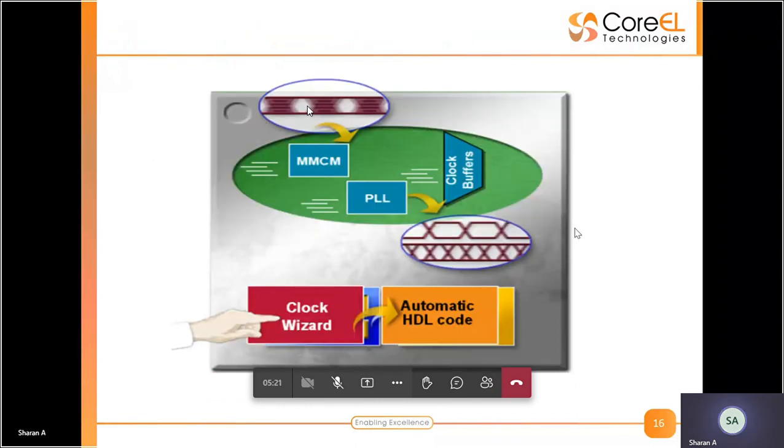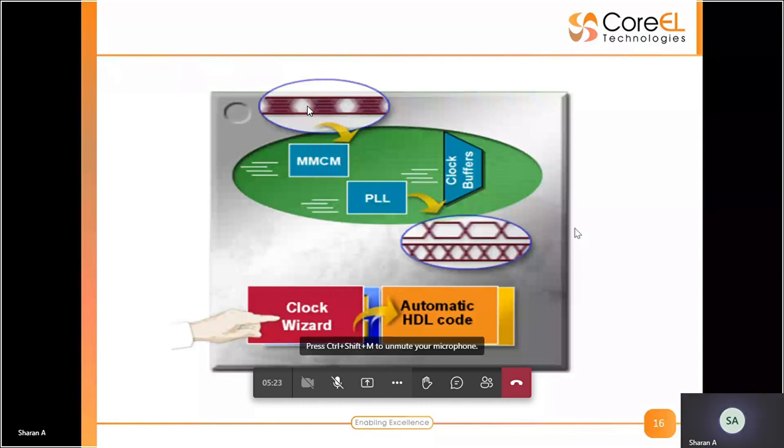So this is a clocking wizard. It's a very useful tool. Suppose your board has a default input clock. Okay, so let's say it's around 225 megahertz. But you have a design, let's say it's a counter. If you directly provide 200 megahertz into the counter, you won't be able to see it counting. It will be blinking so fast, you'll start feeling like it's not blinking at all. Okay, the rate of blinking will be too fast for the human eye to capture.